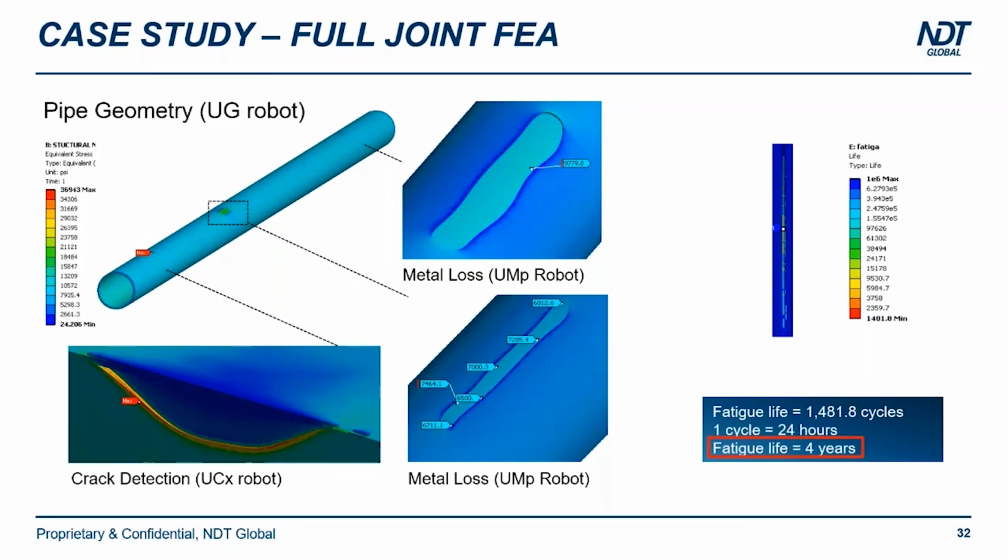The results obtained in this analysis in terms of failure pressure, safe pressure, stress levels, and deformation degree indicated that the pipeline section that contains these anomalies is accepted to remain in service. But now the operator has one assessment with the highest level methodology that supports their decisions about whether to repair, not repair, or repair at another moment.